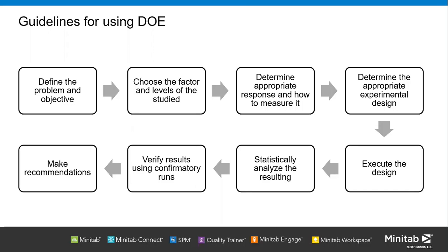of experiment. So maybe one experiment will cost how much, and how much duration you need to take for one run. So from the experimental design, you will know how many runs you need to run, and it will depend on how many factors you decide and how many levels you decide. After that, you can run the analysis based on the design itself.